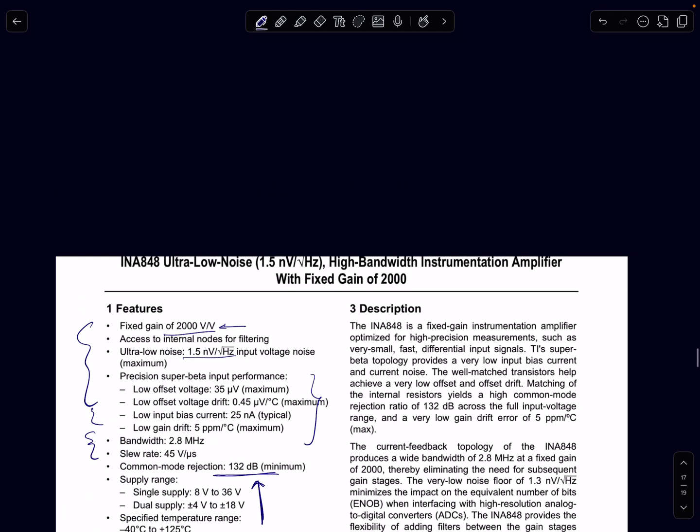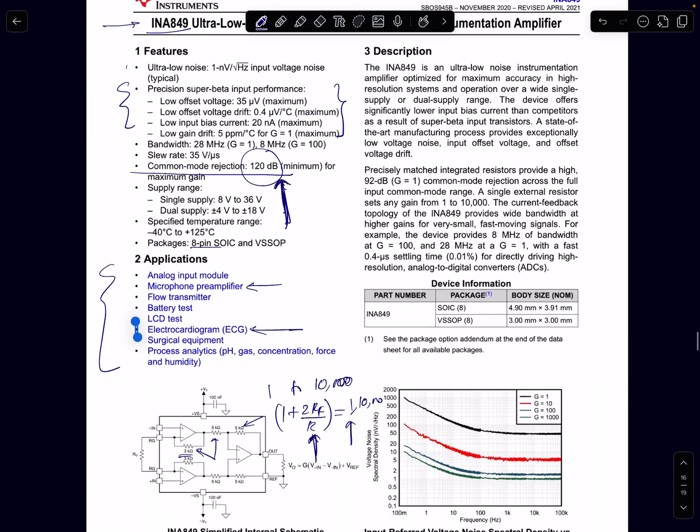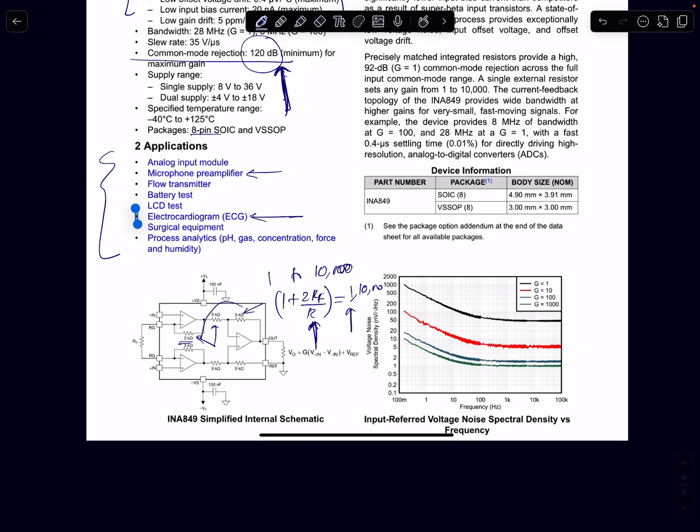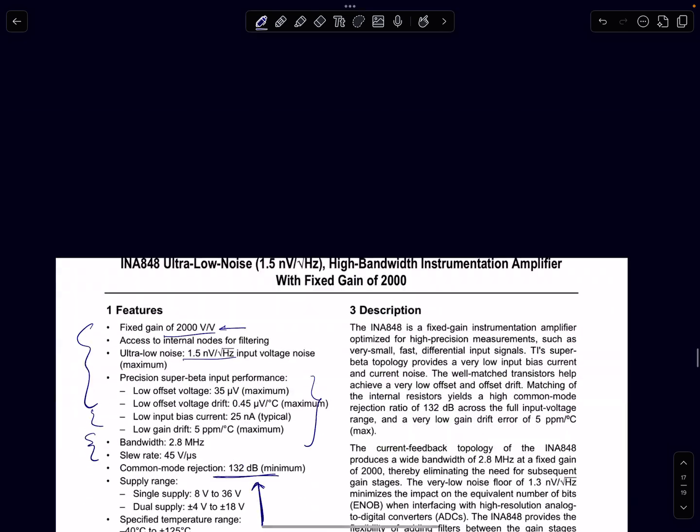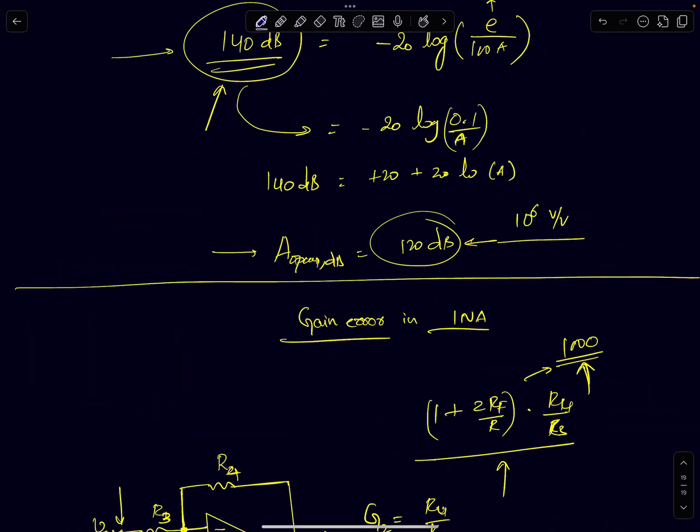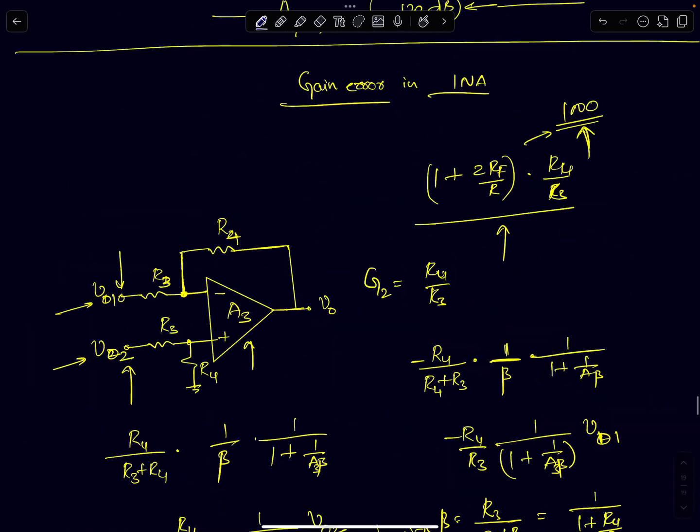And if you look at the other one, the second stage gain is just unity, it's just 1. It's a programmable gain amplifier where all of its gain comes from the first stage. So that's what I said. Most of the gain is generally achieved by varying the gain of the first stage.